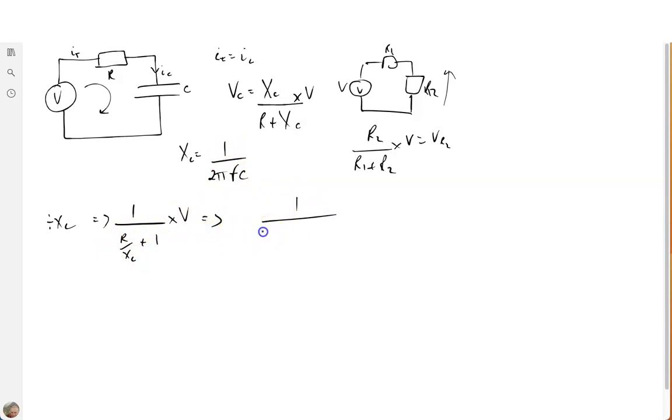This portion of the equation is something that's often referred to as the transfer function. So depending upon the magnitudes that we choose for the R's and the C's, this will give us a proportion of the input voltage that gets transferred to the output, i.e. in this case the voltage across this C. So in actual fact this is an RC filter. As we change F, this ratio of these impedances will change and we will get a different voltage.